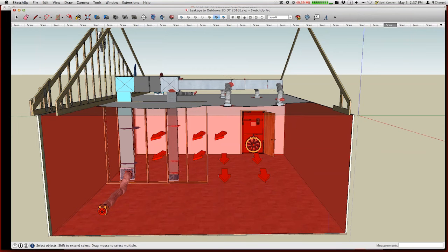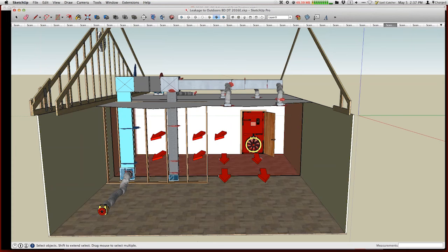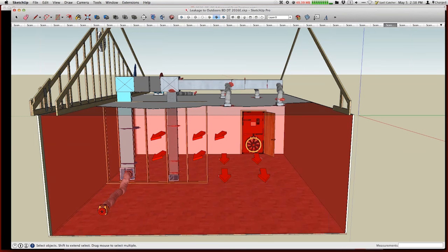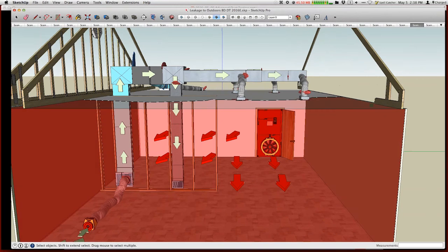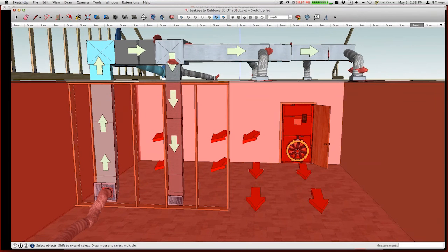So as your normal blower door goes, I've already turned it around. If you have an older system, you can use the switch, but it's a better habit to always just turn it around. I'm not concerned about the readings on the blower door. I just need for it to reach a uniform pressure in the house. Okay, so I have my system set up.